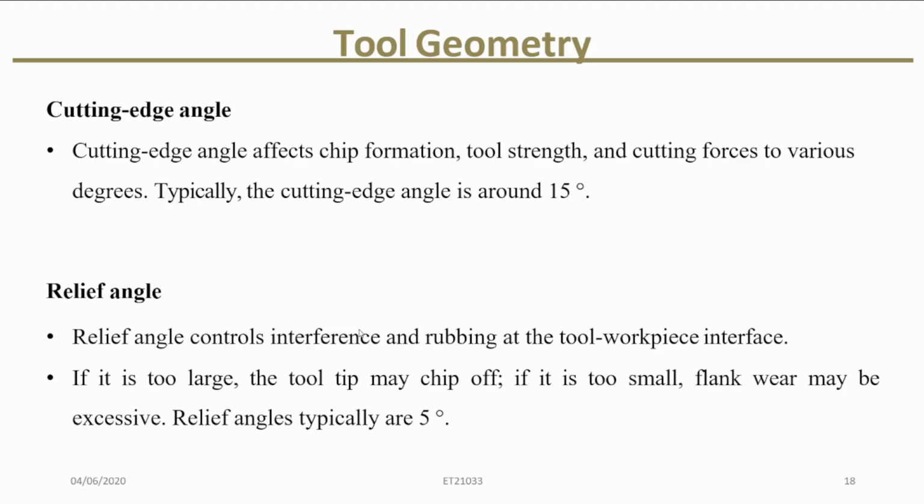Is it clear about the cutting edge angle? And I think at that point we will discuss the relief angle. Okay, so I think it's clear for you. So the relief angle prevents the flank from rubbing the fresh surface.